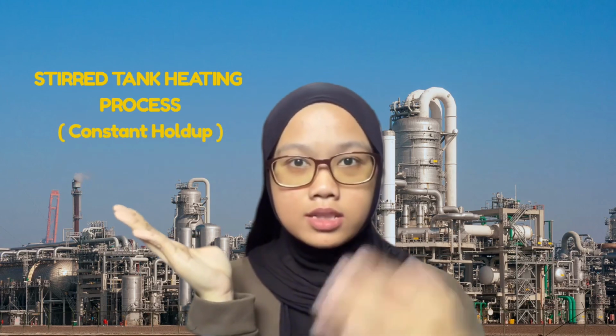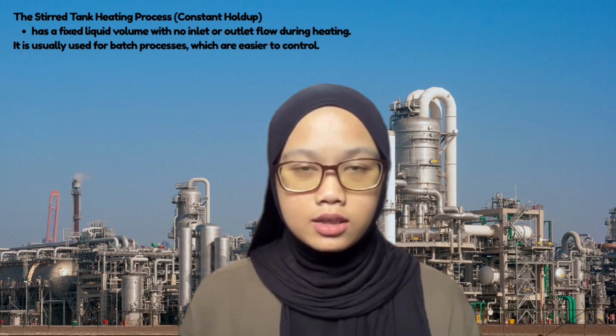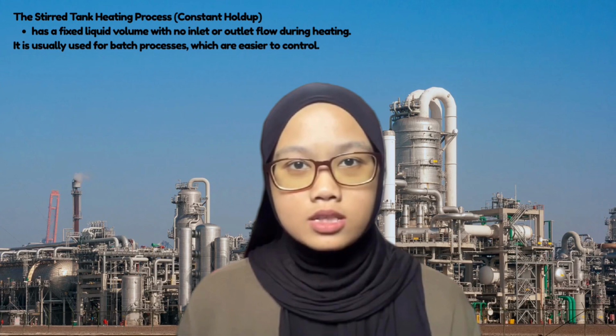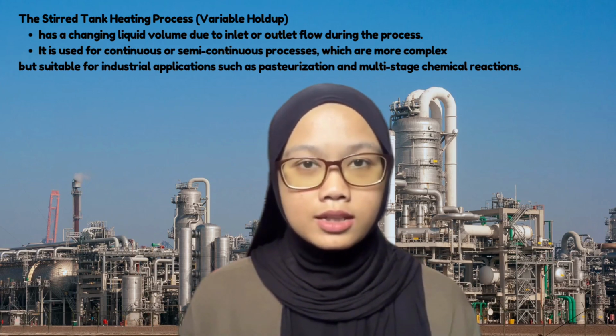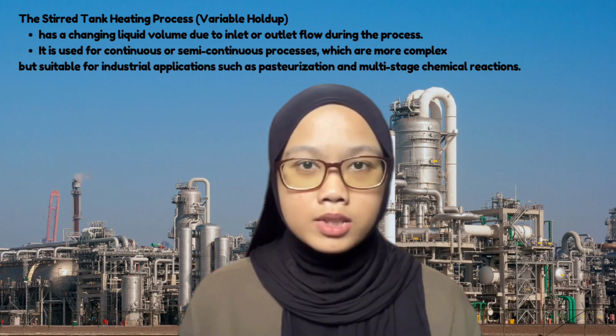So, what is the difference between the stir tank heating process with constant holdup and with variable holdup? The constant holdup process has a fixed liquid volume with no inflow or outflow during heating. It is usually used for batch processes that are easier to control, while the variable holdup process has a changing liquid volume due to inflow or outflow of liquid during the process. It is used for continuous or semi-continuous processes which are more complex but suitable for industrial applications such as pasteurization and multi-stage chemical reactions.